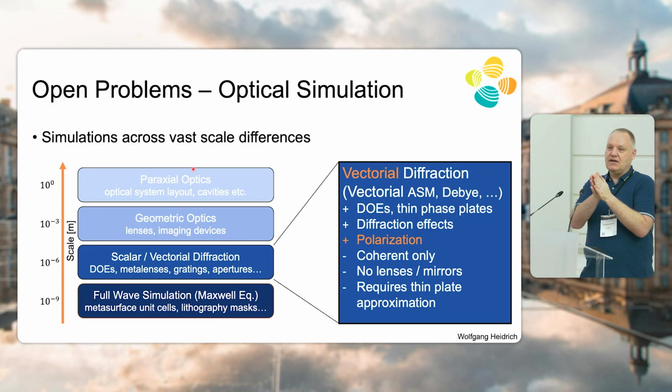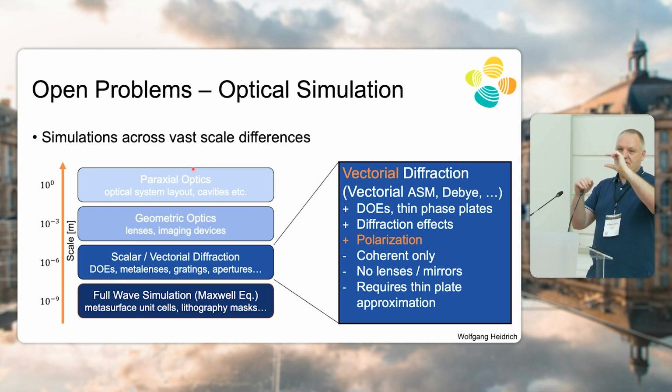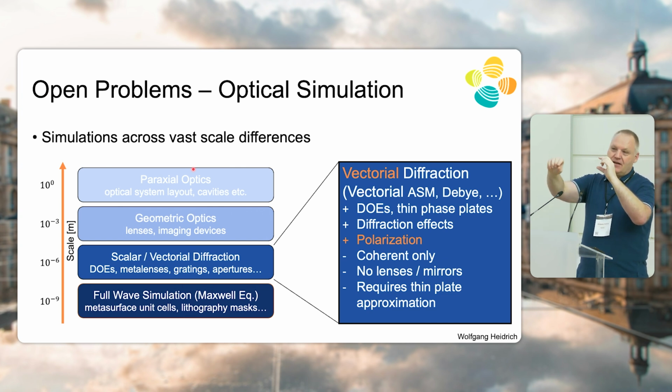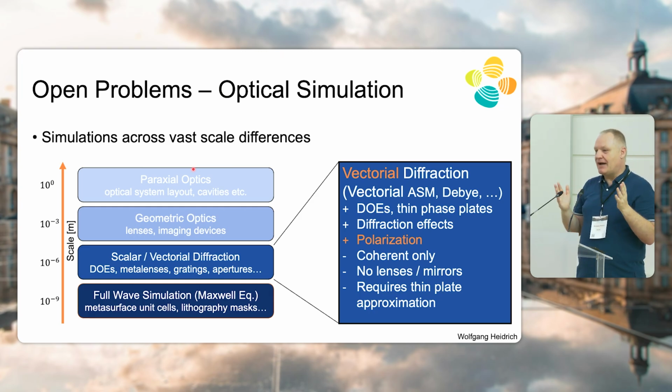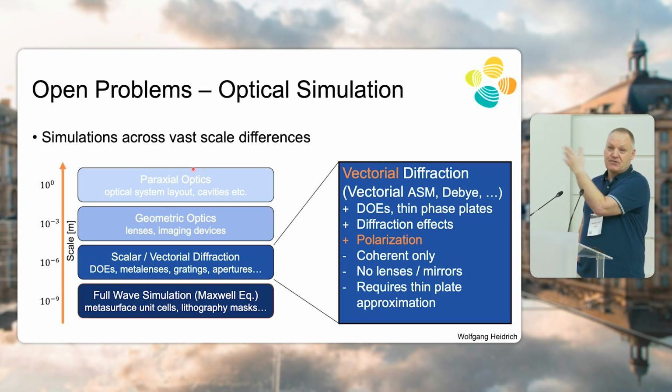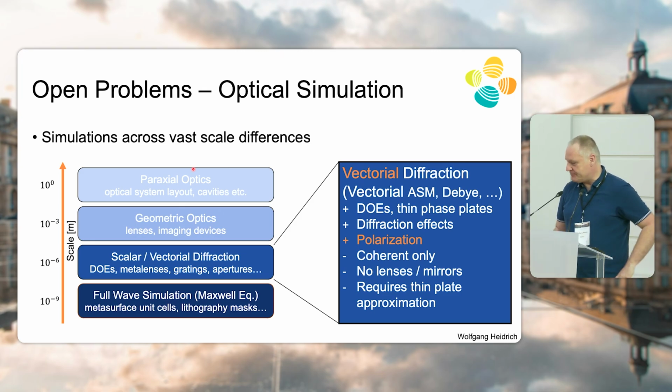If you have a 1 centimeter aperture and, let's say, a couple centimeters propagation distance, and you want to know whether the light hits this pixel or that pixel of your image sensor, that's a couple hundred microradians of angular resolution that you need, right? So you need to be very, very accurate still, even though you're integrating over all these wavelengths. So it's actually a really tough problem.